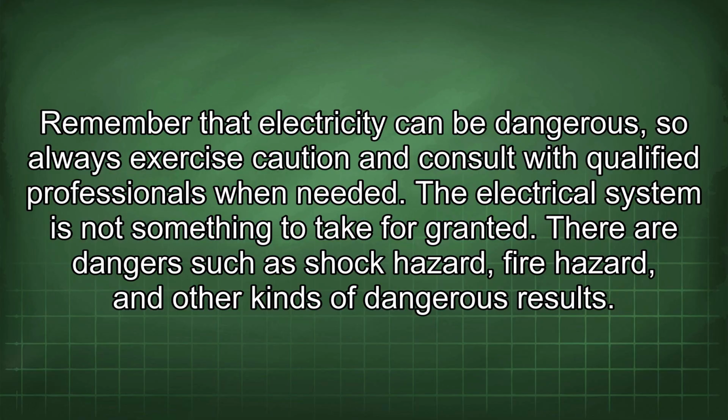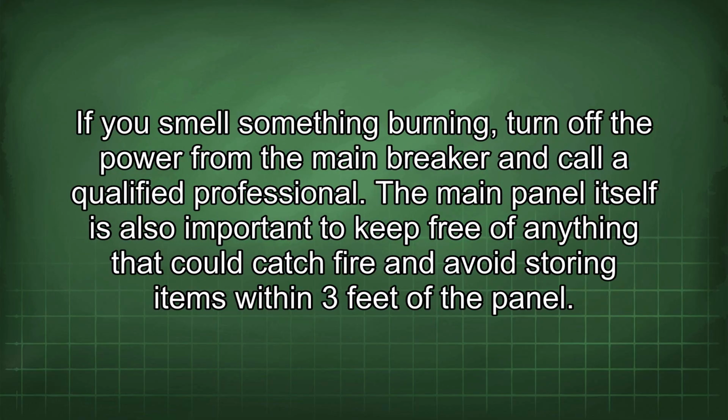The electrical system is not something to take for granted. There are dangers such as shock hazard, fire hazard, and other kinds of dangerous results. If you smell something burning, turn off the power from the main breaker and call a qualified professional. The main panel itself is also important to keep free of anything that could catch fire, and avoid storing items within 3 feet of the panel.